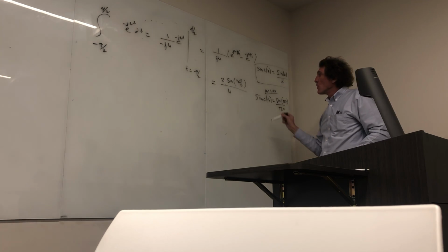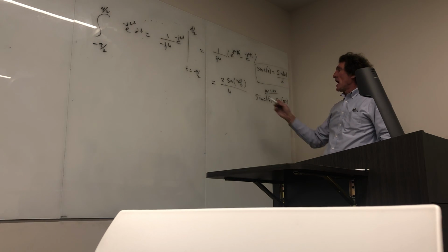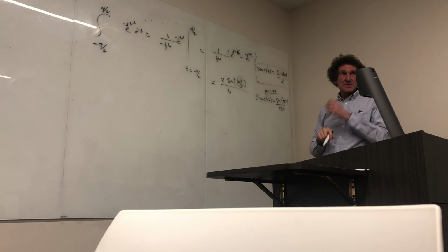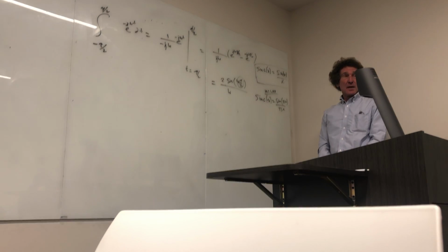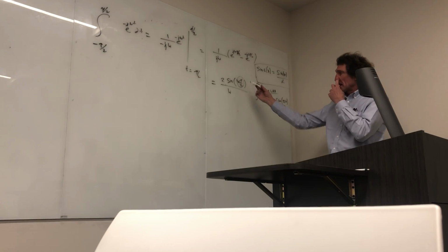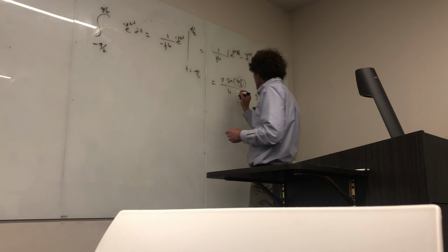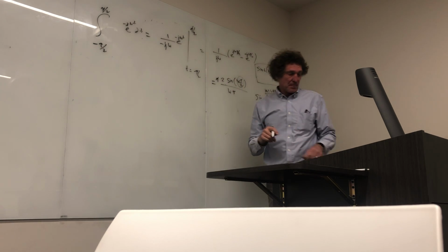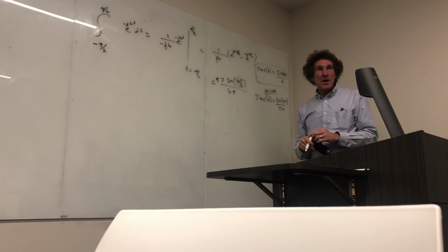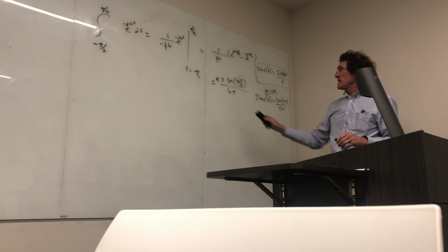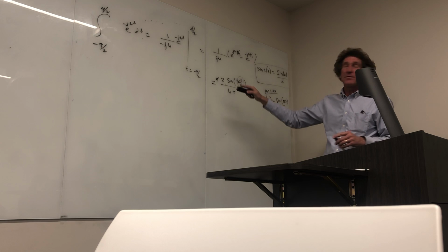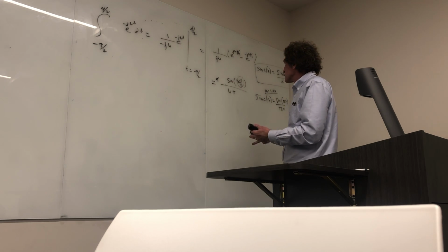All right, now, when I take a look at this, I need to have this argument appear down here if I want to turn it into a sinc. Agreed? How do I get it? Well, I need a tau. I put a tau here, and I put a tau here. It's that simple. Top and bottom, didn't change the value. I need a half down here, but I have a 2 up top, so I divide top and bottom by 2, and now I have this.